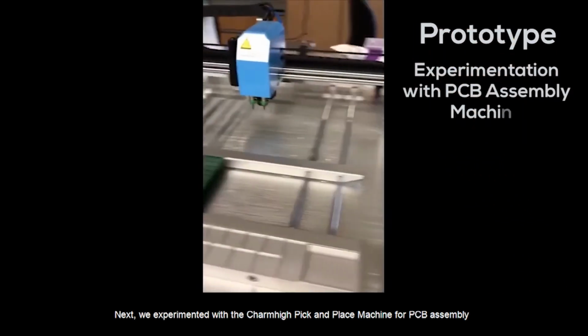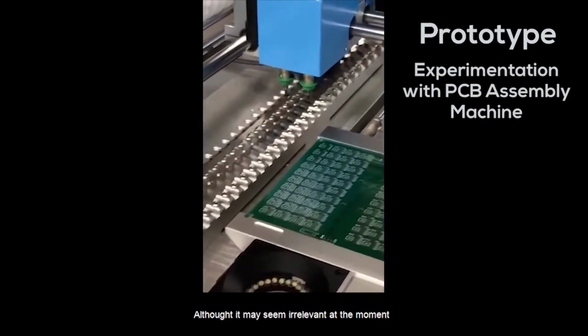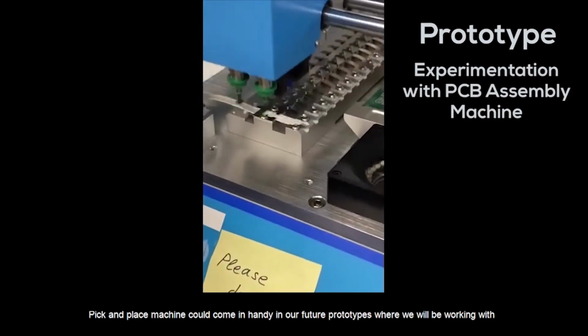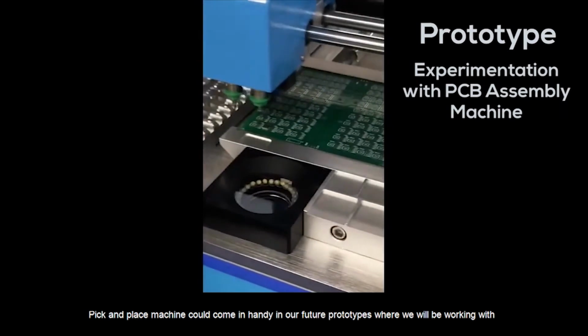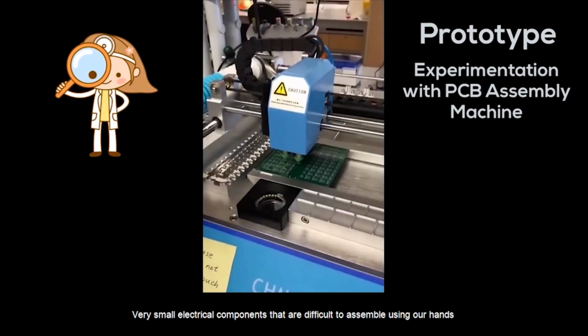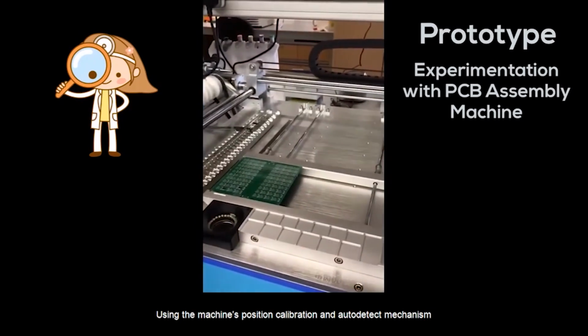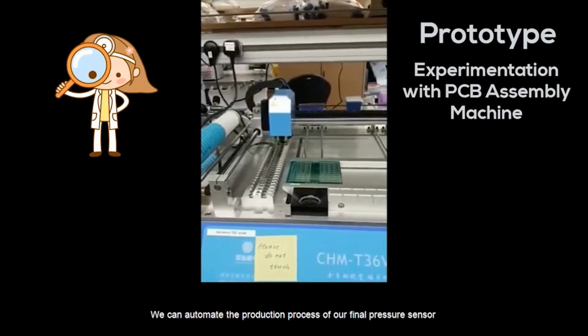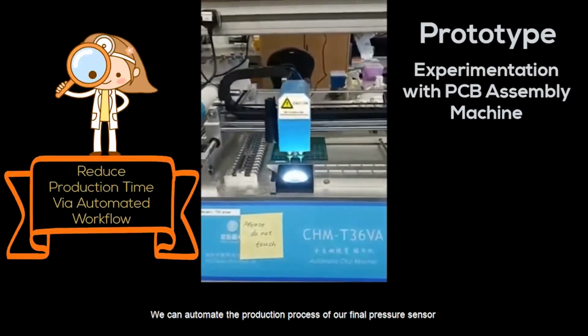Next, we experimented with the Cham-Hai pick-and-place machine for PCB assembly. Although it may seem irrelevant at the moment, pick-and-place machines will come in handy in our future prototypes where we will be working with very small electrical components that are difficult to assemble using our hands. Using the machine's position calibrations and auto-detect mechanism, we can automate the production process of our final pressure sensor.